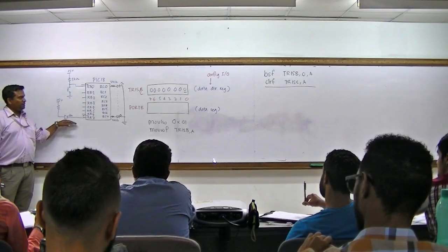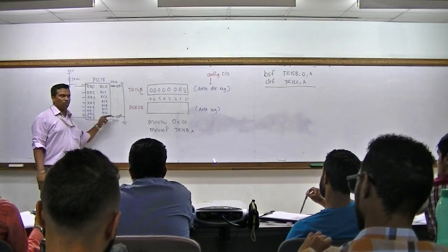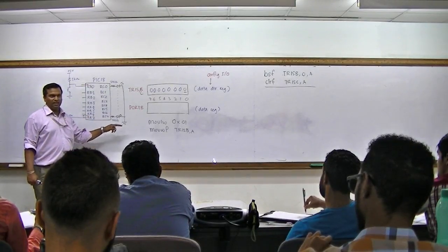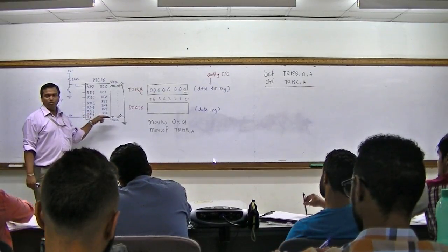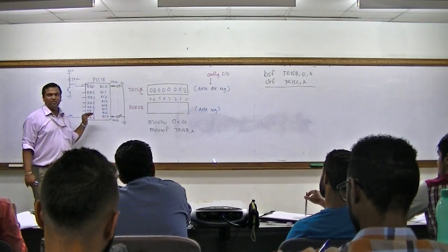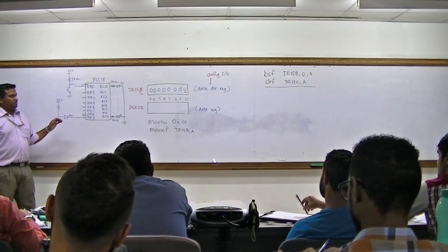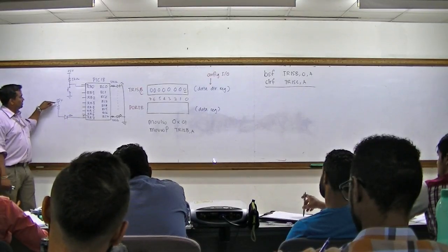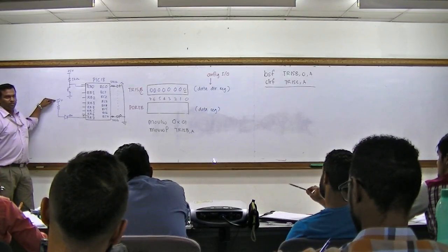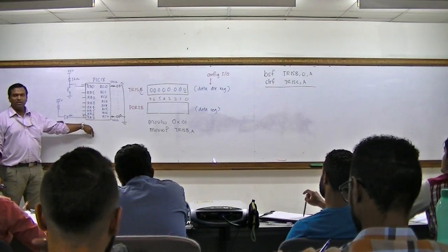Now this one is better than the other one, because in the other one the power comes from the microcontroller. It is supplying the current, which is more power consuming because it is giving the output. Whereas this one is allowing the current to sink in. That means the current source is coming from elsewhere, coming in, going here and going down to the ground.